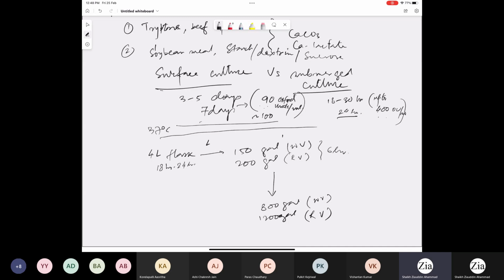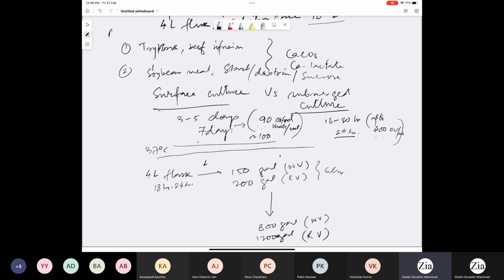Here you do the autoclaving of the media in an appropriate manner, because I mentioned that sometimes you add calcium carbonate salt. When you do this operation, you don't mix everything together, because if you sterilize the carbon source and nitrogen source along with calcium salt, you will end up getting precipitation.